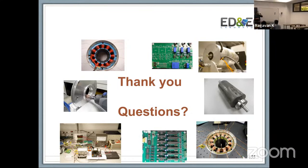So for this kind of fault detection, technically, yes. The idea basically was that we were going geometry agnostic. We were going with the assumption that we don't have any information about the motor at all, which means we are going with a black box. So when you have a brand new motor, no matter what it is, if it has the flux, we establish what a healthy pattern looks like, and from there, we evolve it to the place of having a failure.